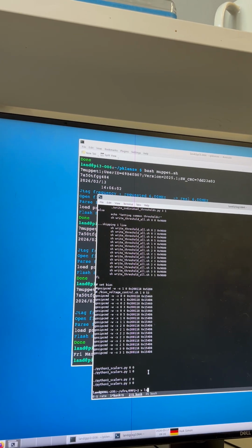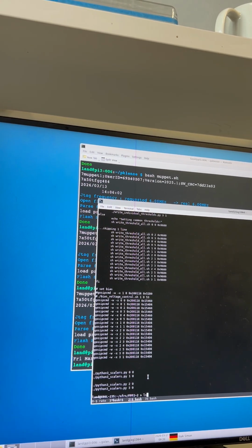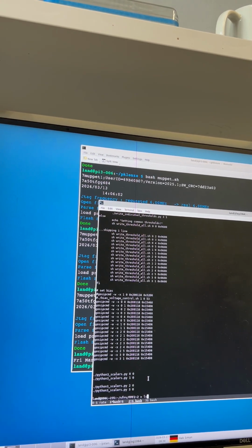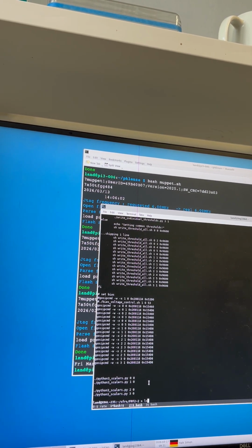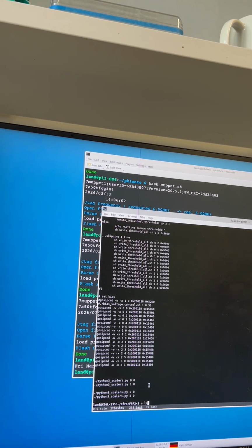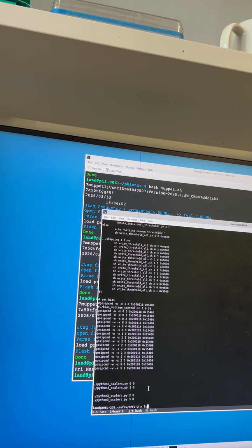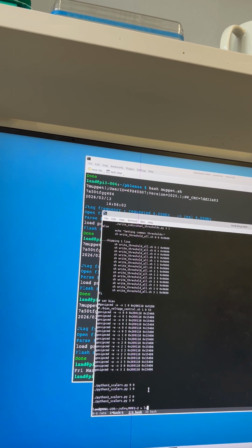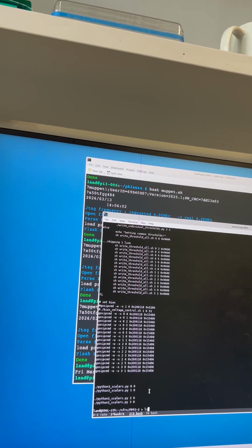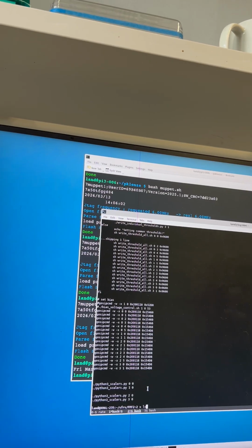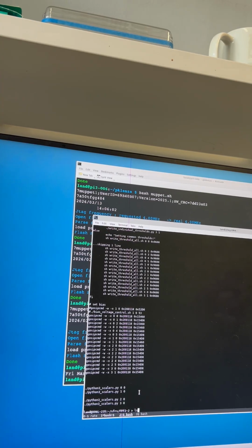But at the beginning you will read as a scalar value 0, and then it takes a while until the voltage is on, because the voltage is ramped very slowly. So you have to wait a minute. We don't want overshooting of the voltage, because then this IPM is dead. So we go from lower values to higher values rather slowly, and go to the value from the bottom, never overshooting. We need ramping up, that's for sure, and we don't want to overshoot.